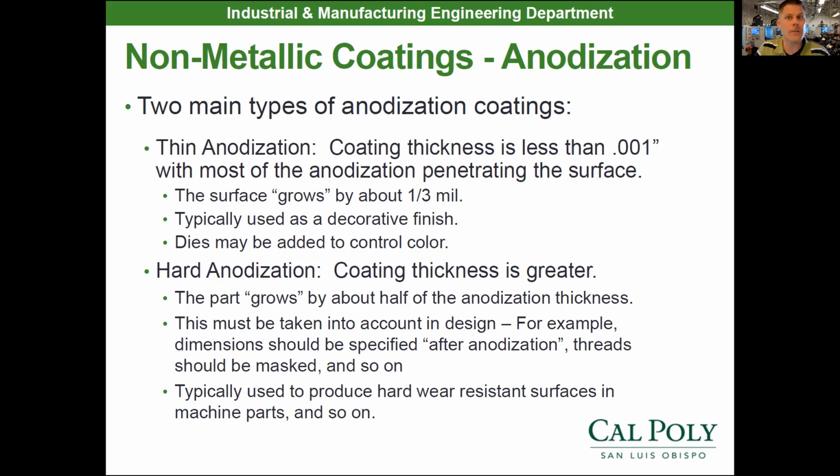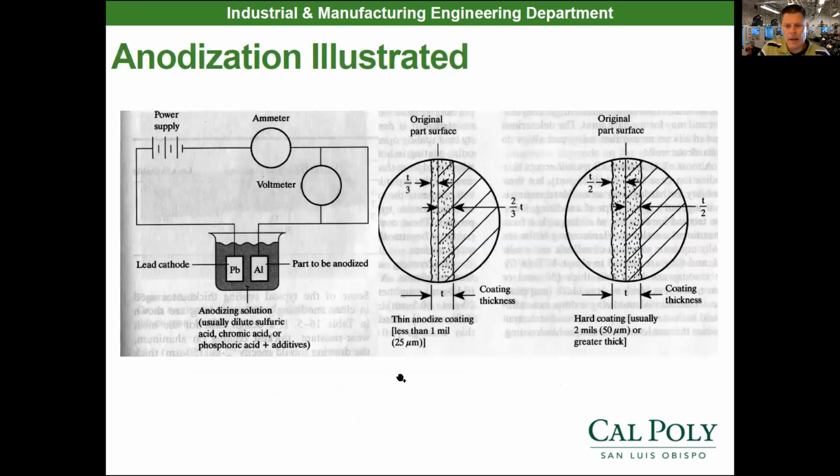All platings and surface treatments add material to your workpiece. You've got to be worried about that not fitting into the assembly after you paint it. So definitely look at how much your process is going to add in terms of thickness to the surface. Powder coat, basically metal plating, all of these add a little bit of material. So these hard anodized parts are usually done as wear resistant surfaces on machine parts. You're going to see there are lots of parts that get hard anodized out there.